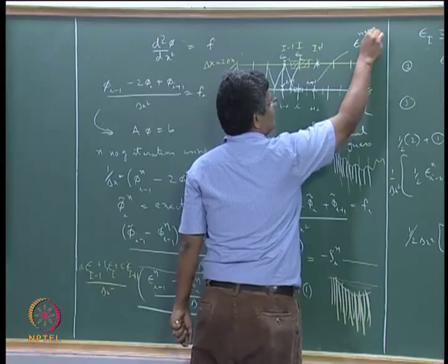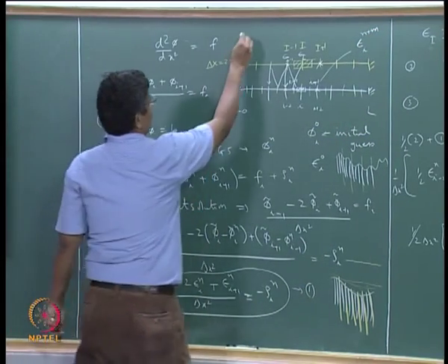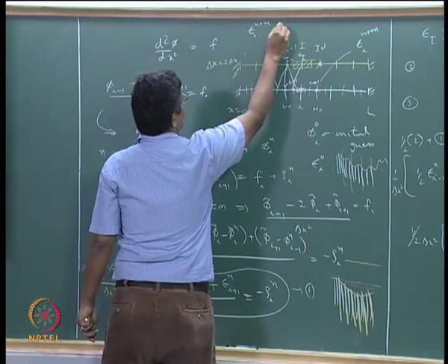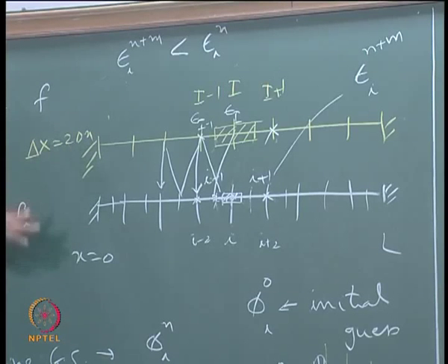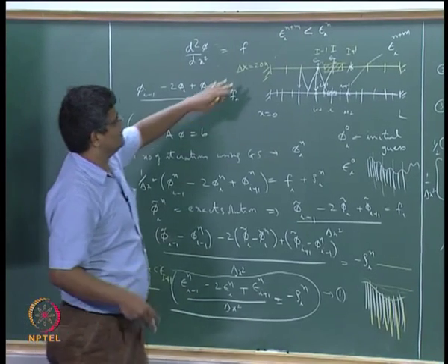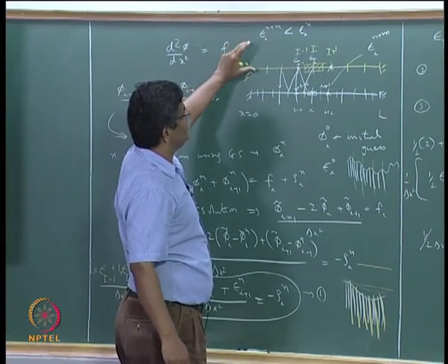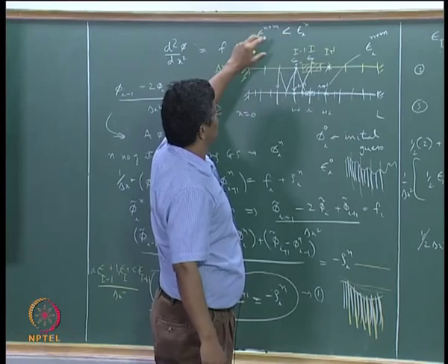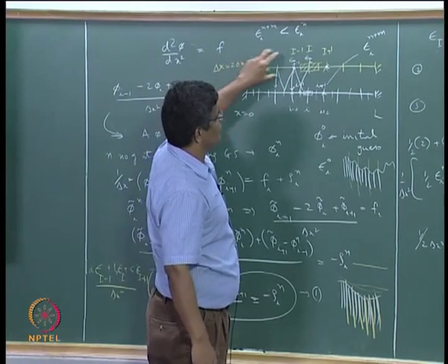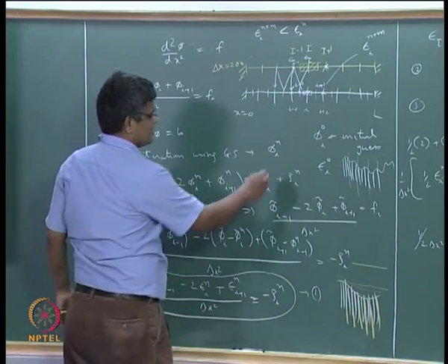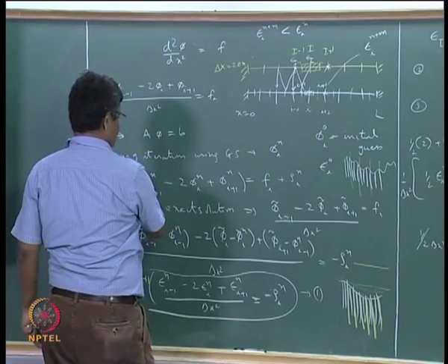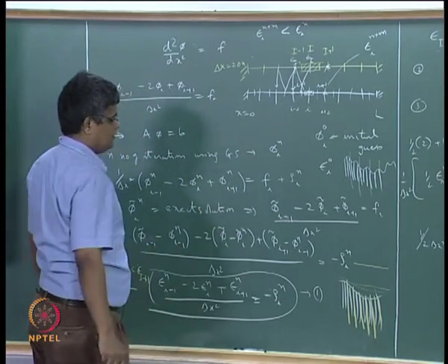At the end of n plus m iterations, the error is less than the error at the end of n iterations, because this is a Gauss-Seidel method and it is convergent, and we have probably gotten into asymptotic convergence. So we have carried out some reduction of error by doing m computations on the coarse grid, and then once we have this error we can get a revised estimate for the phi value and go back into this equation, and then we can do further calculations.